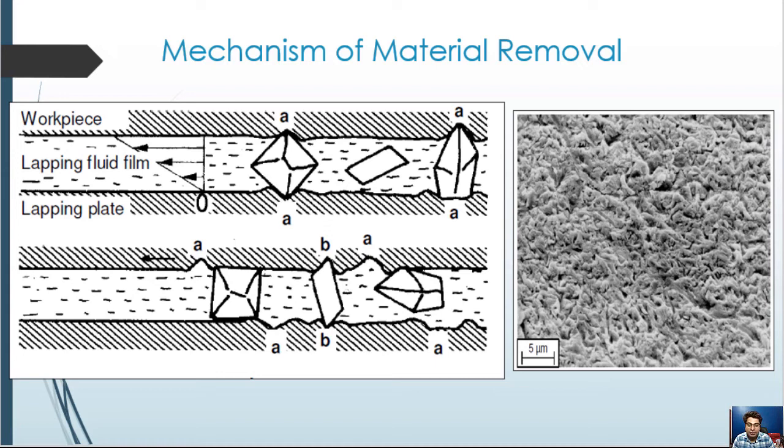The surface receives its appearance through the overlapping of the crater-like traces of the total indentation from engaged grain edges. Groove-shaped processing traces, suggesting material removal caused by the cutting process, are not visibly recognizable. The material-dependent hardening is associated with an embrittlement of the material and is indicated by an increased surface hardness.